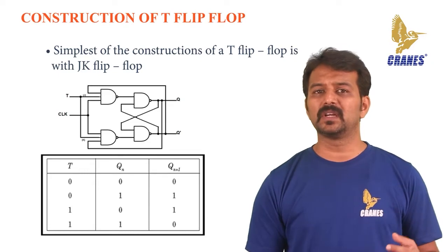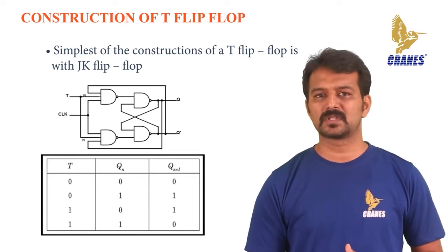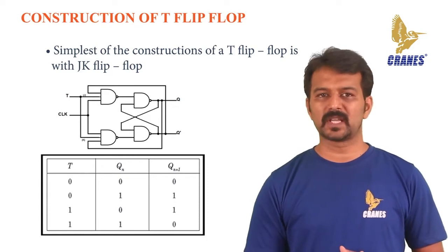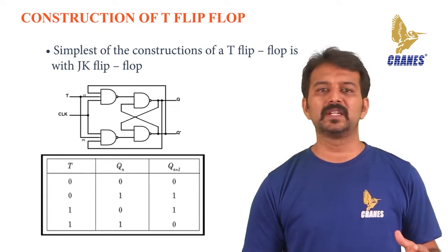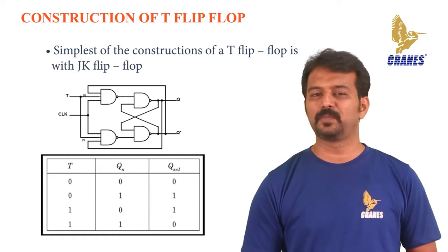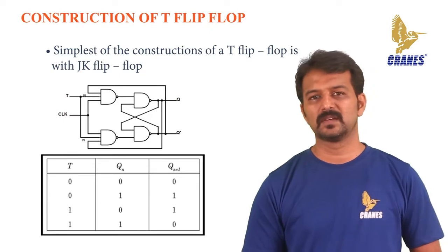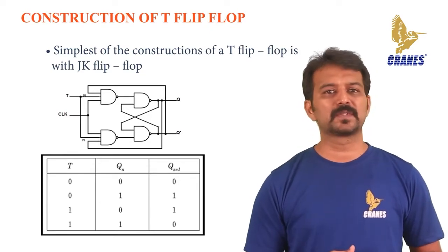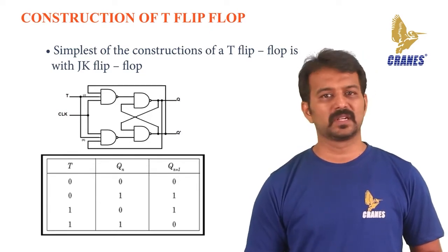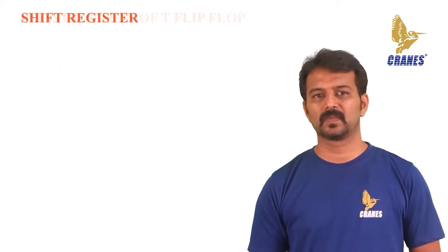As each incoming trigger alternately changes the set and reset inputs, the flip-flop toggles. So, to complete one full cycle of the output waveform, it needs two triggers. This means that the T flip-flop produces the output at exactly half of the frequency of the input frequency. So, a T flip-flop will act as a frequency divider circuit. This is one of the applications of the T flip-flop.